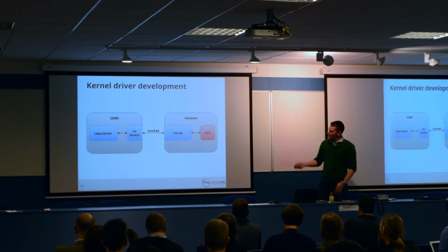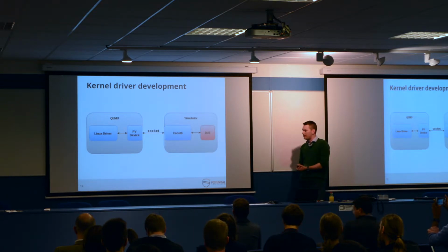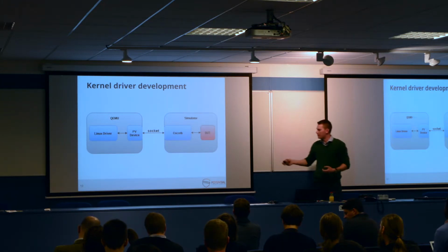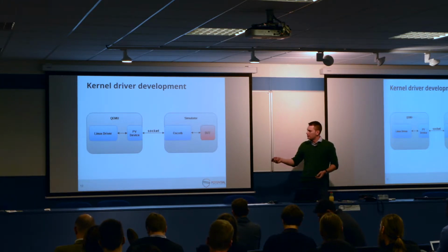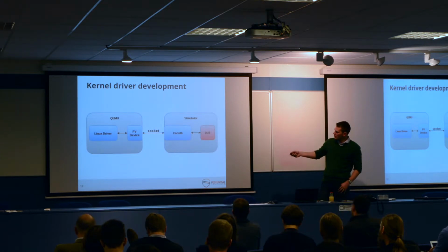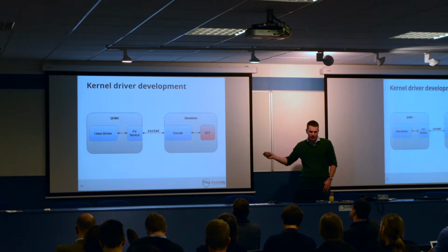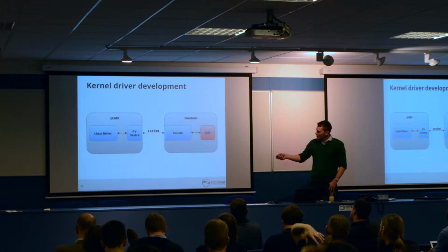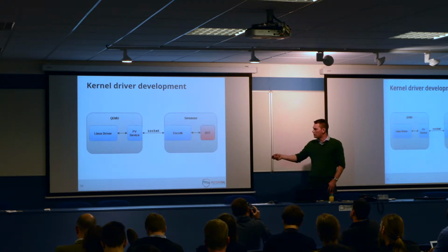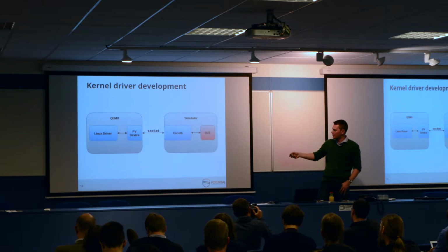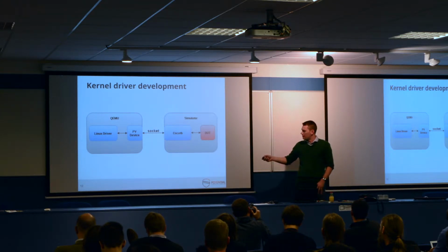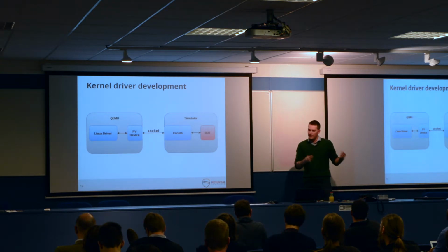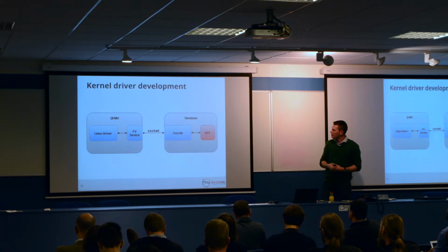And yeah, so this is primarily for doing PCIe devices. So as QEMU boots, it communicates with the simulator to get the base address mappings for all the BARs. We then create a device in QEMU. Any DMA from the simulator gets sent over the socket, and we update the QEMU view of the memory map. And similarly, any accesses from the driver we trap and we send over the socket. So we've got a transactional level model abstraction here between QEMU and our simulator. So we can develop kernel drivers in QEMU against our RTL running sim.